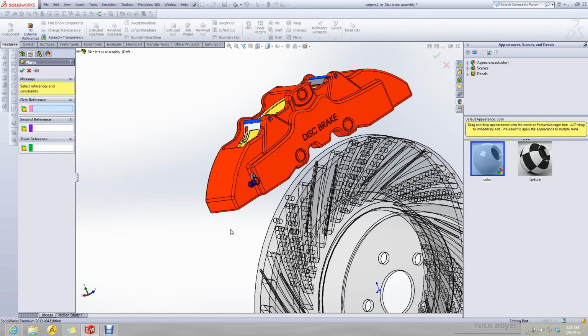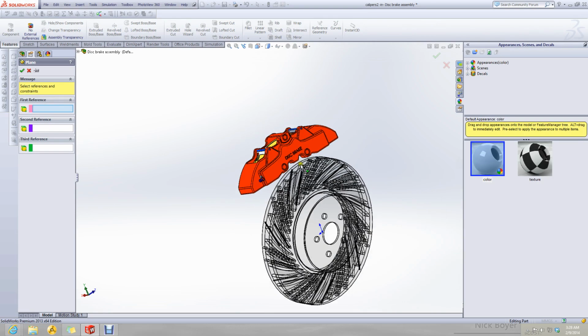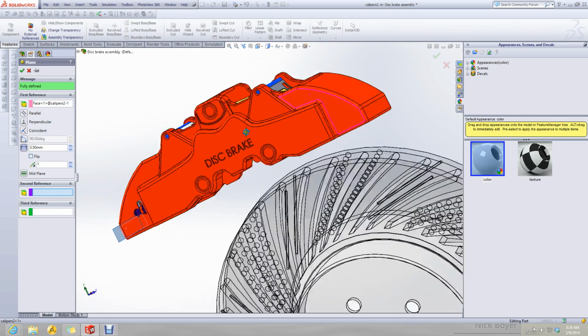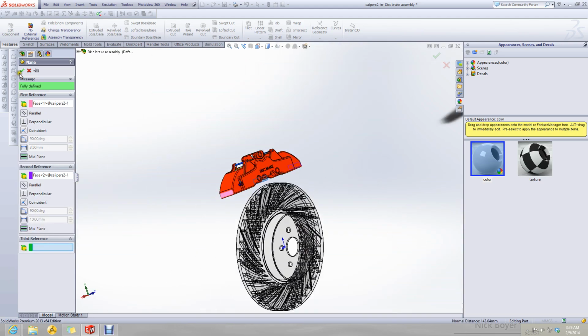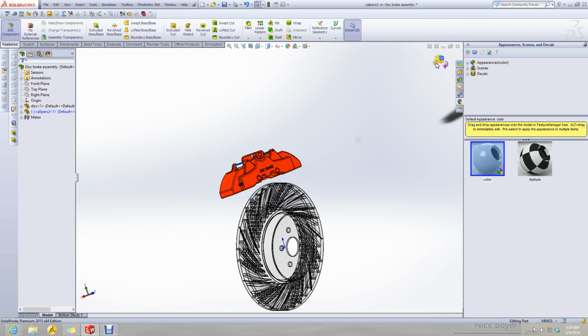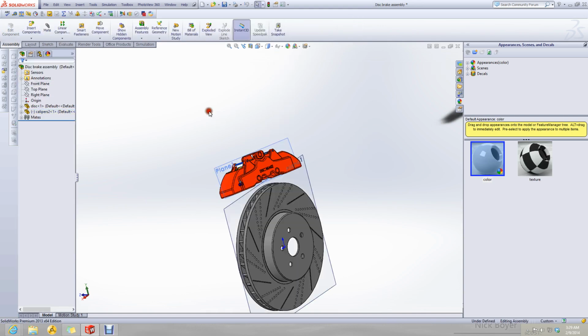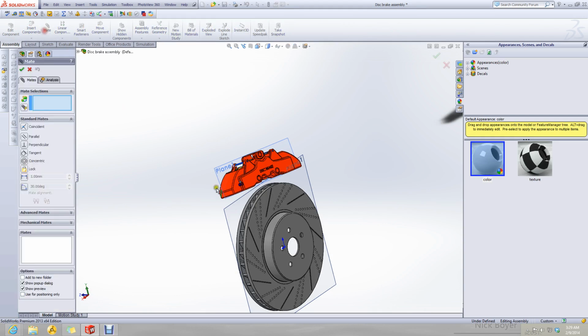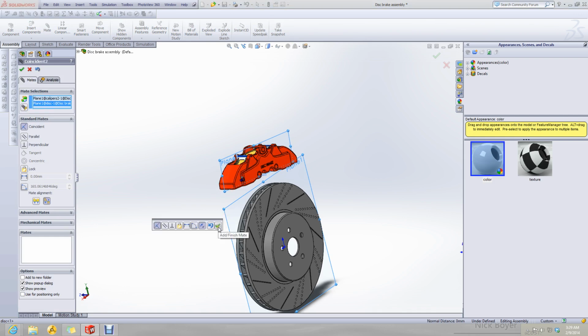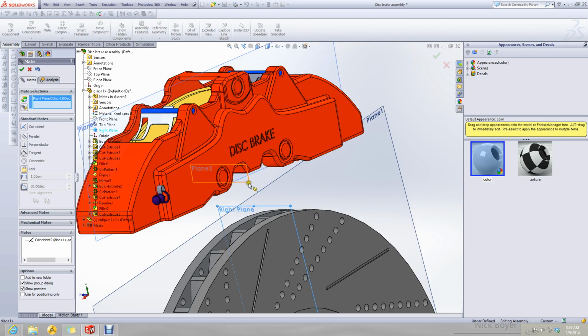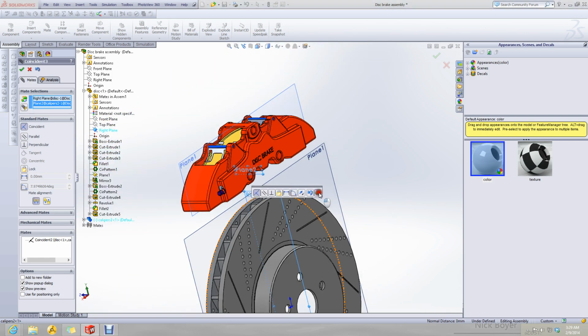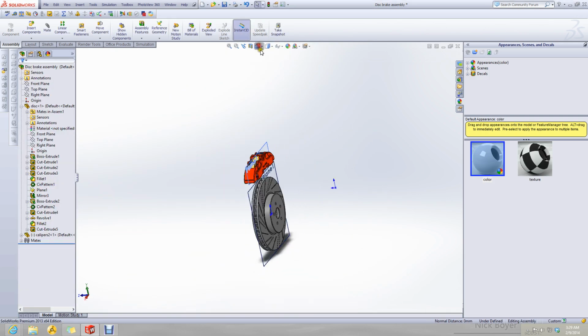To draw any plane between the middle of two faces, you just click those two faces and the plane is created between them. So just to align them, I have created these two faces. Now turn on the face plane. I made these planes now like so, and I will make the right plane of the disk with this plane. Here it goes.